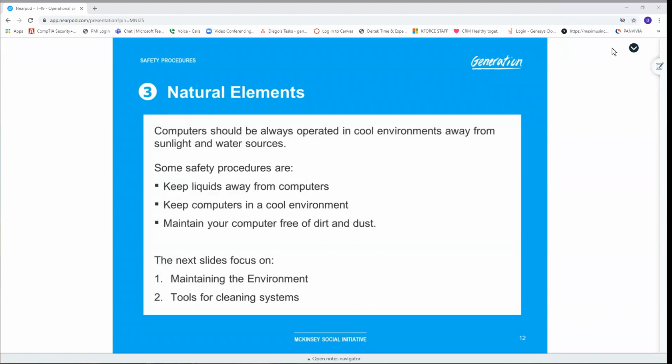Corrosion, rust, oxidation. So if you have too humid an environment, your components could actually start to rust and will not function properly. What happens if we have too low humidity? What is a danger of that? That's electrostatic, right? Electrostatic, very good. So if we have too little humidity, we get static electricity. Too much humidity, we get corrosion.